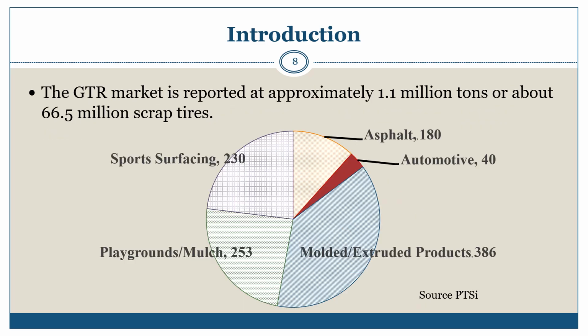Recycling of waste tire rubber from tires into GTR involves grinding or reduction of tire rubber into smaller particle size, which results in an increase in surface area. The rubber grinding industry classifies GTR according to particle size as rubber which is 2.0 millimeters, 10 mesh, and smaller. The typical size of GTR used in modified asphalt binders and mixtures for pavement construction ranges from about 1.5 millimeters or 1,500 microns down to about 0.42 millimeters, 420 microns, 14 mesh to 40 mesh, with limited use of sizes as small as 177 microns or 80 mesh, and even 125 microns or 120 mesh.